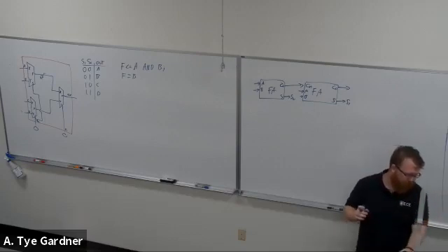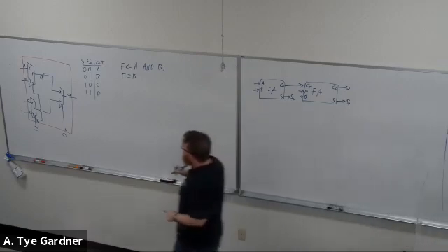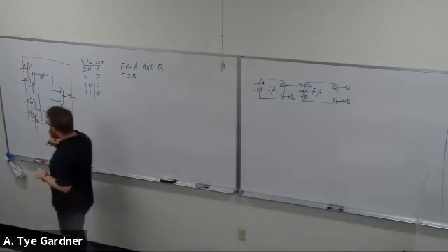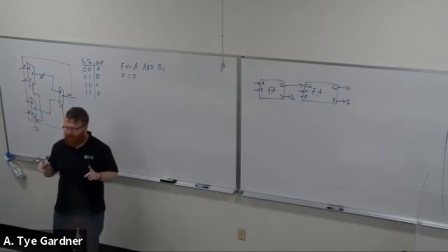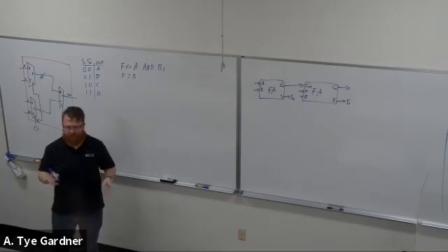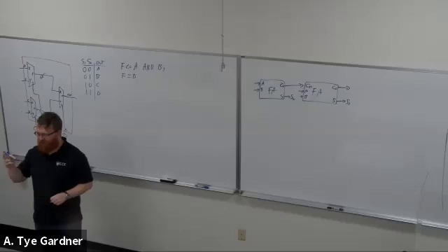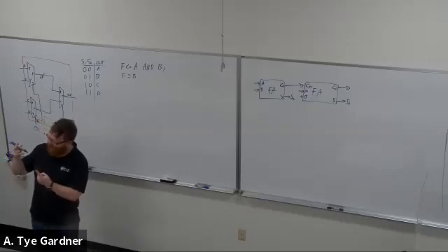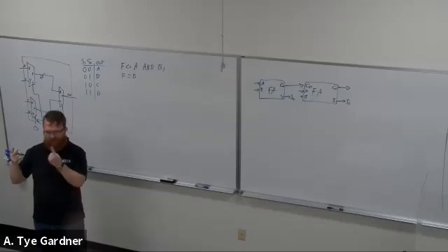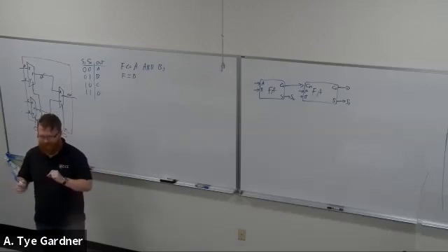Okay. Now, let's go ahead and introduce one more type of assignment statement, which we're going to use to make a mux. Muxes are very important and for some reason very confusing in the past when I taught them, so I'm hoping this solves that. Because all the mux does is take two inputs and then a select, and this puts on the output one, A or B, depending on select. No other logic goes in there. It takes exactly one line of code to make a mux.